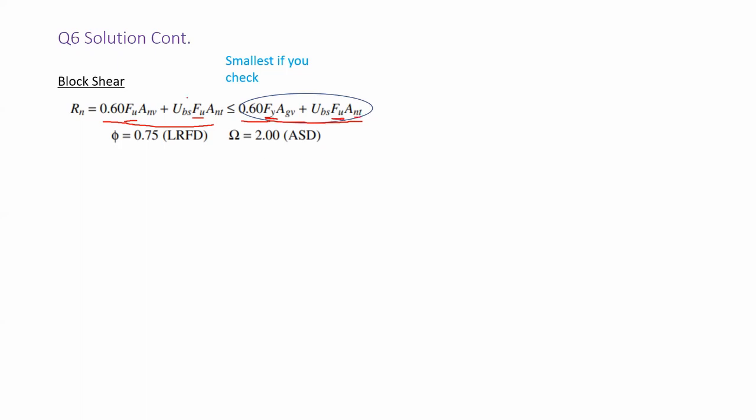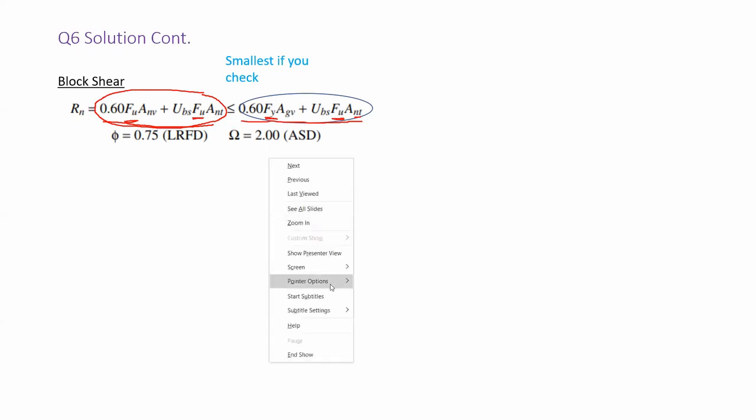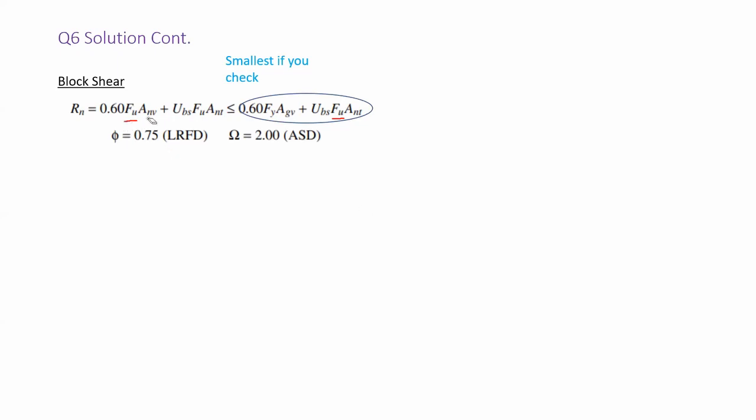Now, if the case was that this part is the smallest, you will notice that it is saying to us that the part in shear would actually rupture. It will totally cut, and the part in tension would totally cut also. So you have a separate piece. Since we have found out that this part is the smallest, the part on the right-hand side,